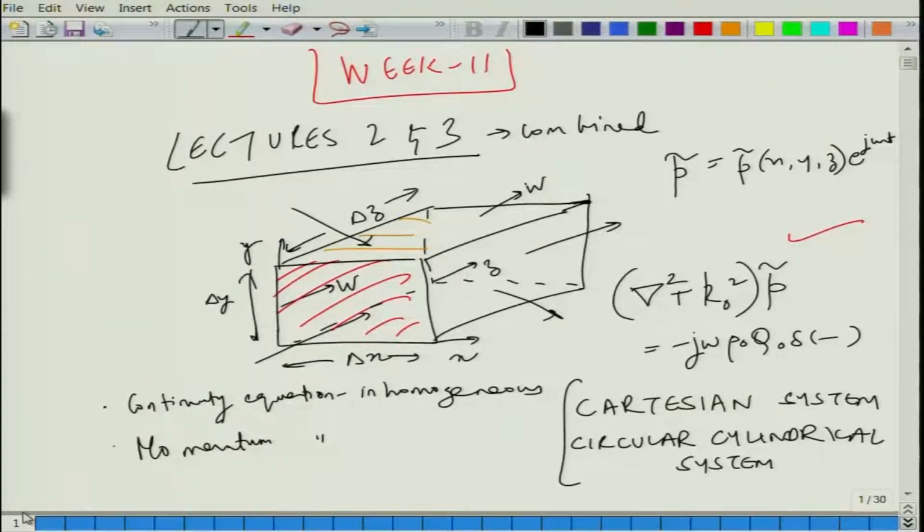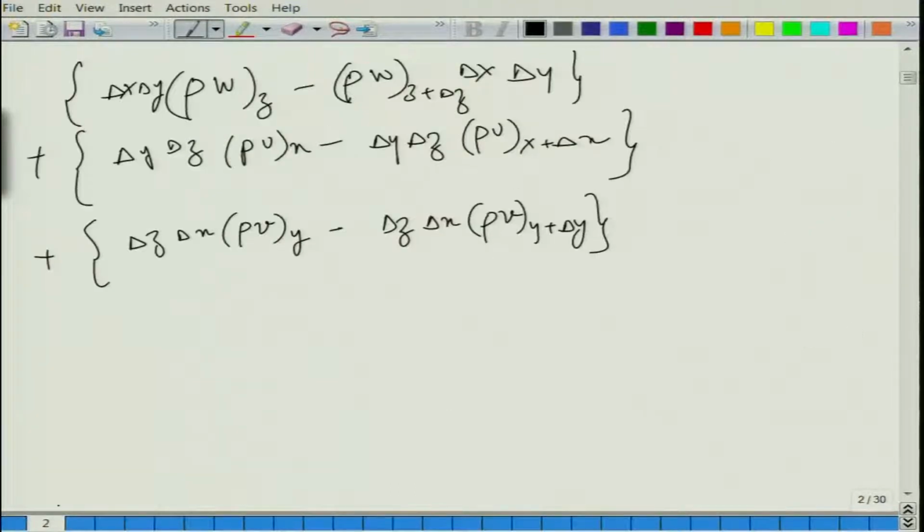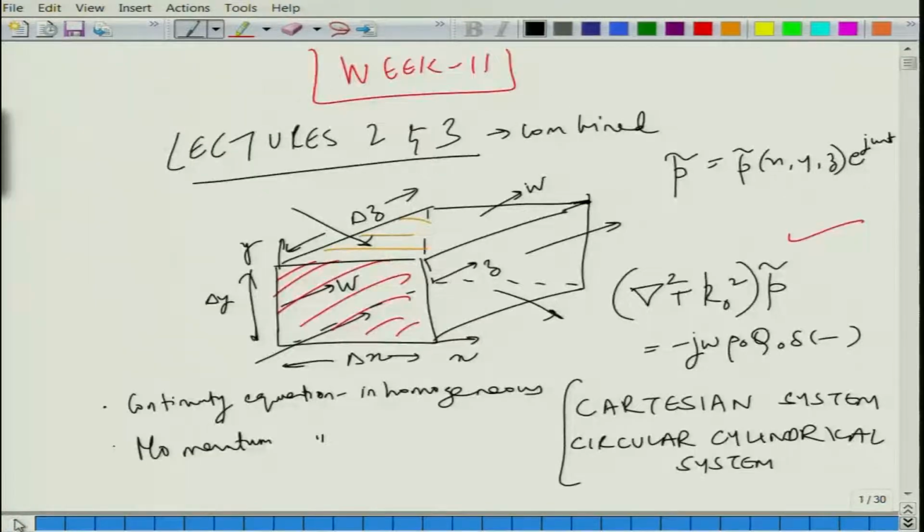So, this is the net mass flux that is created within the differential volume, mass flux that comes inside, leaves, comes inside and leaves, and so on, and this is equal to what, plus all this while we were equating this thing to the net temporal change of the mass inside this volume, that is your density times the volume. So, we have this particular guy sitting here. So, this is a small elemental volume, obviously in a Cartesian coordinate system, delta x, delta y, delta z.